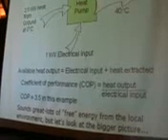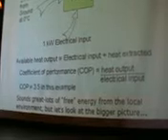So it sounds great. It sounds like you're getting lots of free energy from where you are. But if we just look at the next slide, at the moment, most of our electricity comes from fossil fuel power stations, and those power stations are very inefficient. They're only about sort of 35 to 40% efficient. So at the moment, if we look at running a heat pump from a fossil fuel source, we burn a fossil fuel, we end up with about 30% of it, a third of it left, and then we get a third back, 3 times back from our local environment.